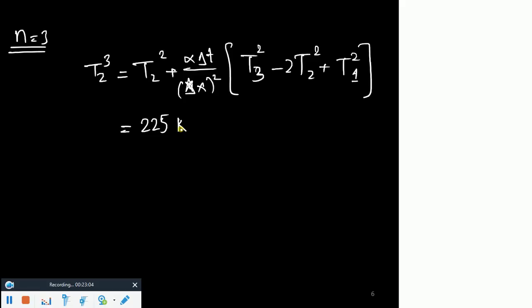You understand that? So you see, there is a large fluctuation. Temperature has gone down. So you remember that plot which I showed you in the stability discussion, that it was at 273, then it was at 298, then it comes down to 225. Is it possible to have that? So it is a non-physical solution. You see, that's how violating stability conditions just gives you wrong results. Have I clarified my point?